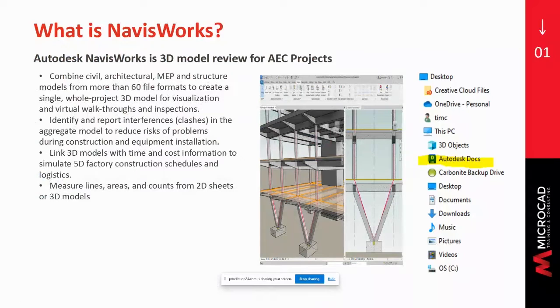So, you see there, link 3D models with time and cost information to simulate 5D construction schedules. That means take the 3D model, the fourth D is time. So that's an animation, or what we call our Timeliner in NavisWorks. And then the 5D can add cost information. So you're not only animating the 3D building of the model, you're also adding cost information to that as well. Okay. And then you can do some measuring and counting areas and getting counts from 2D sheets if you're doing some estimating, et cetera.